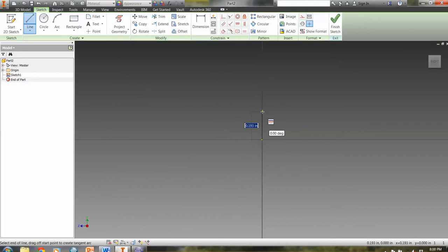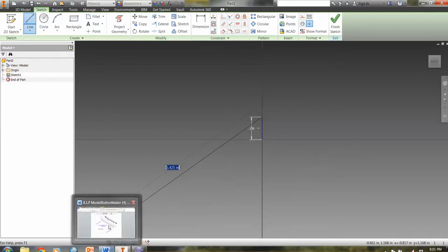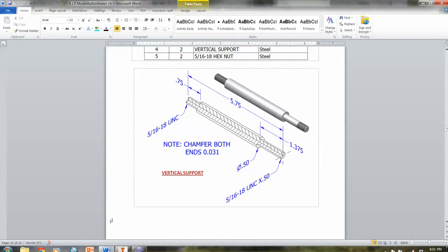So we're going to create that 5/16 into a radius. Easiest way to do that, I'm going to use the power of Inventor. I'm going to type 5/16 in parentheses, divide that by 2 to create the right size that I need. It will do the math for me. Then I'm going to add in the other dimensions as I get across here and create the whole shape.